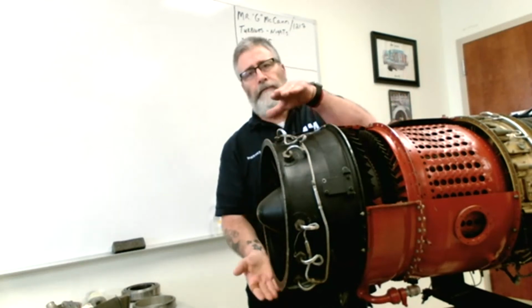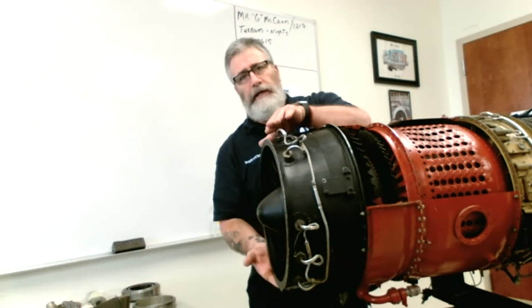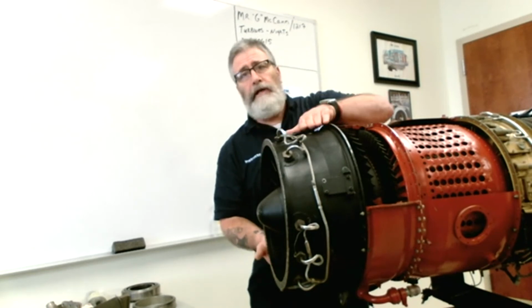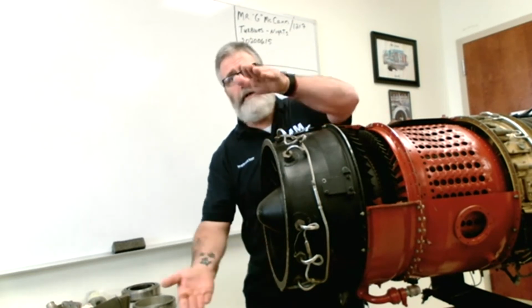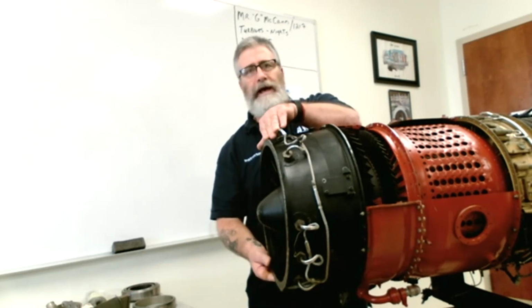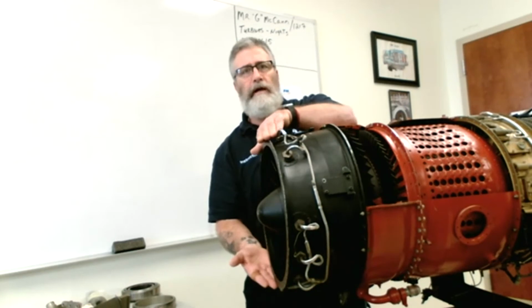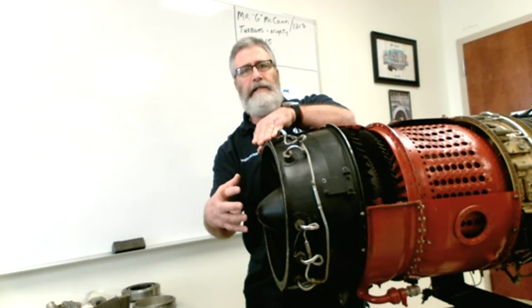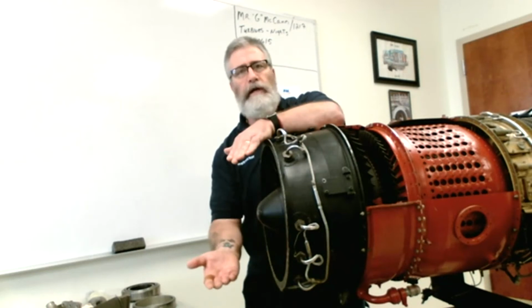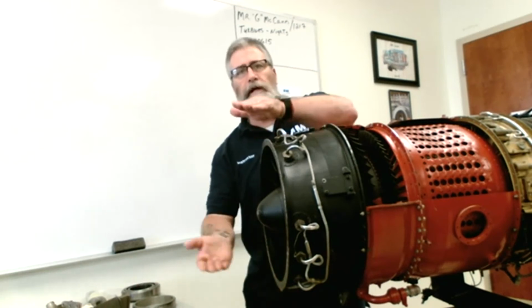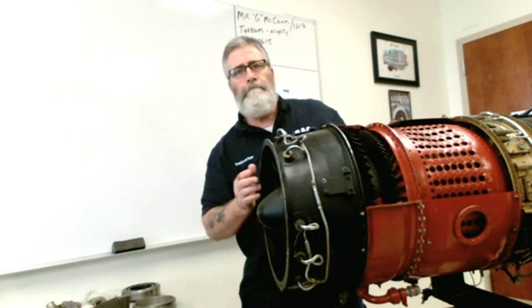Now, the exhaust is always convergent on subsonic aircraft. However, when we get into supersonic aircraft, the exhaust has to be convergent and then divergent, right? There's no easy way to explain that other than the fact that at Mach speeds, a traditional convergent exhaust will actually start to choke off or block itself because it can't handle that type of acceleration. So they have to open that up. So supersonic aircraft use a convergent-divergent design, all right?